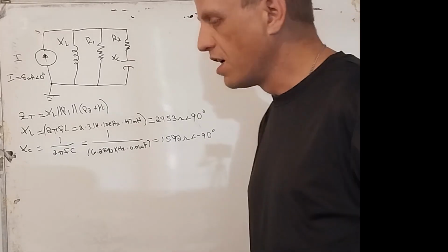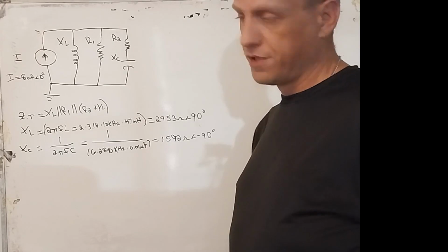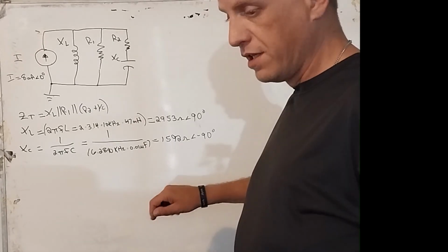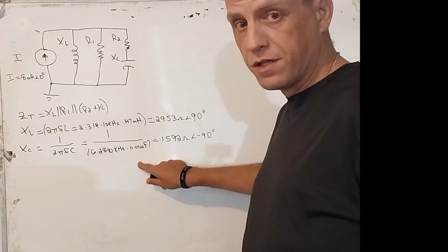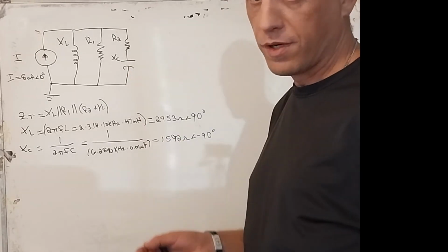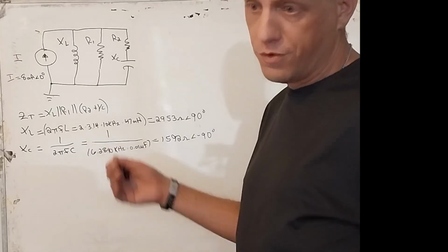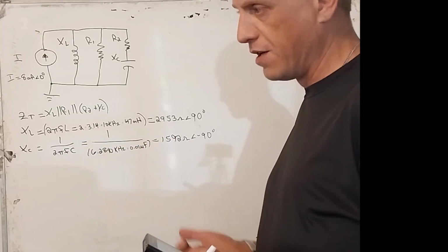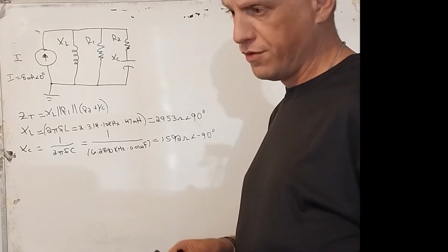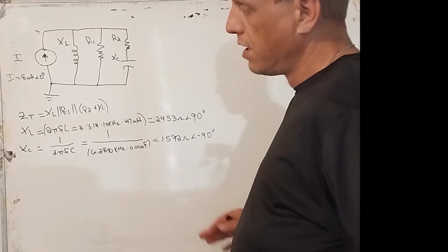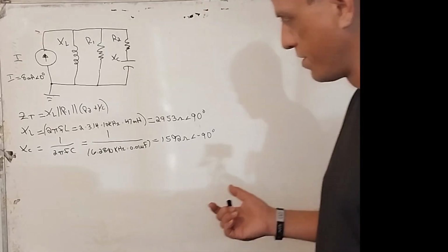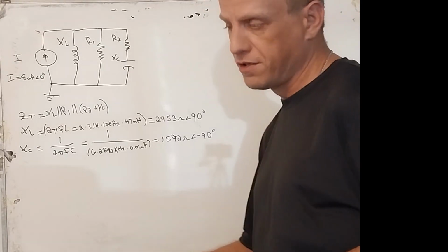And if we have an inductor, I'll probably show this on an actual practical circuit, because I could hook up an AC. I could use a function generator to create an AC waveform, or I could just use a transformer and do it the right way and use the outlet on the wall to do 120 volts. If I step it down to 12 volts using rectification and all that, I could probably make a pretty useful voltage supply for DC or AC circuit analysis.